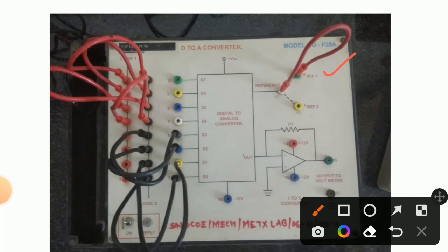When wires are connected in this form it is logic 1, and when they are connected in the other it is logic 0, so these are called logic 1 and logic 0 lines. Like this, here we get input as 1 1 1 1, and here we get 0 0 0 0. This is the input right now, and we have to measure the output voltage over here with the help of a digital multimeter.